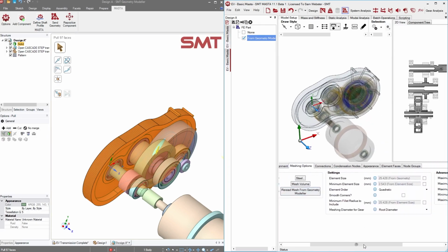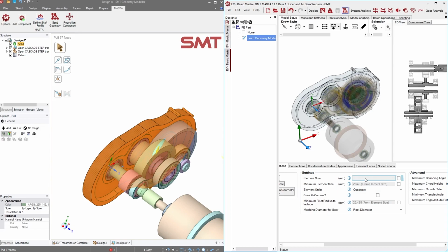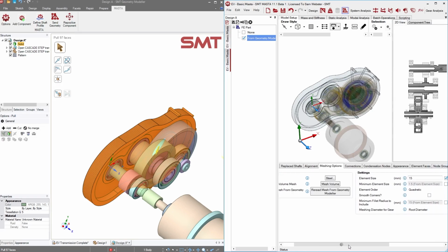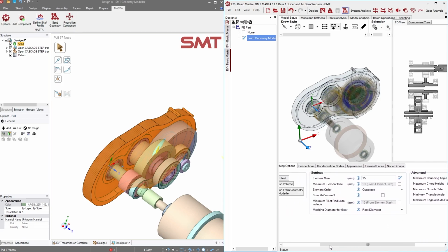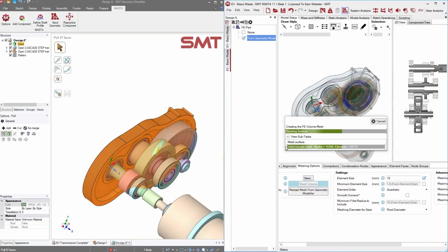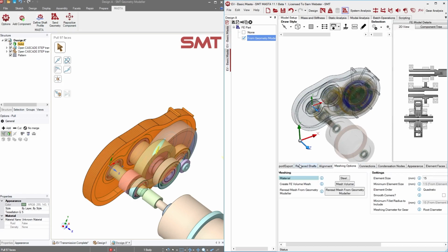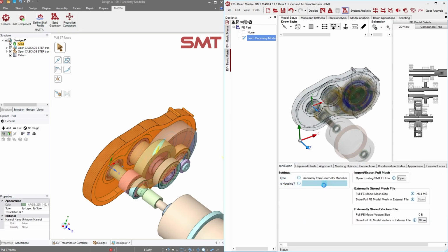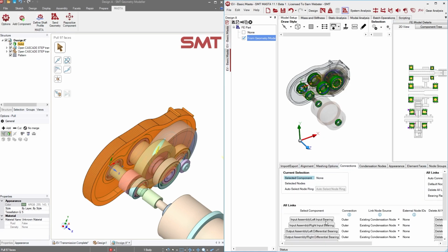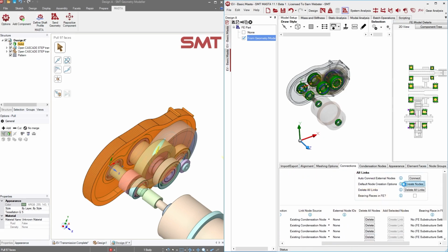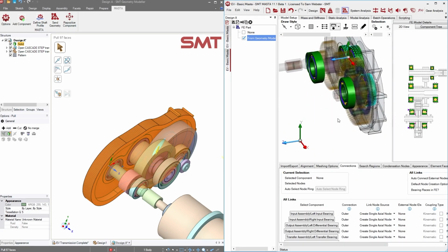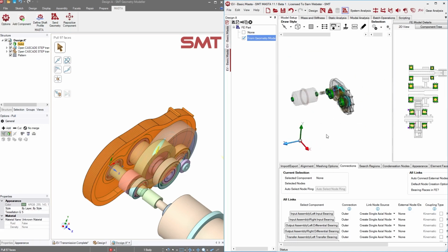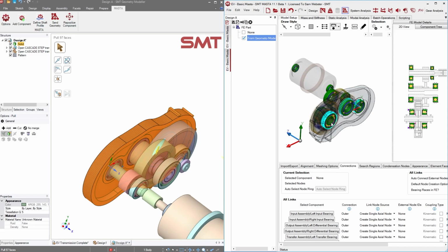And then, as we've seen previously in this webinar, I can go forward, generate my mesh, convert it to an FE component, and then utilize it in my model. So you see there, for example, I now have connections for those 3 bearings. Of course, we would need to complete the housing, but that will do for our little example in this respect.